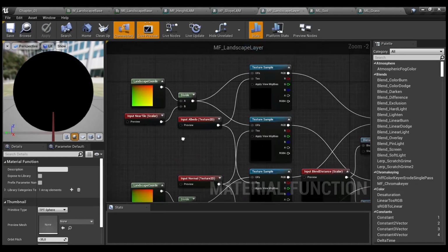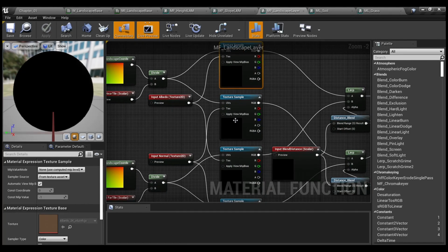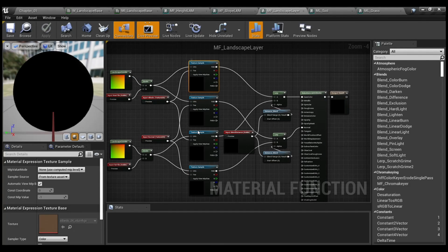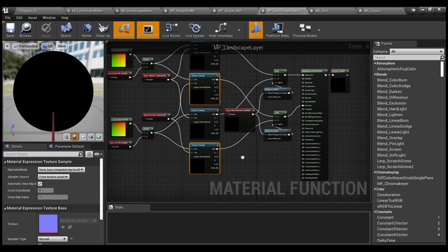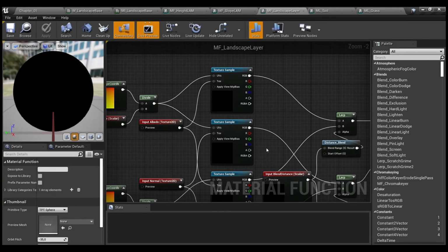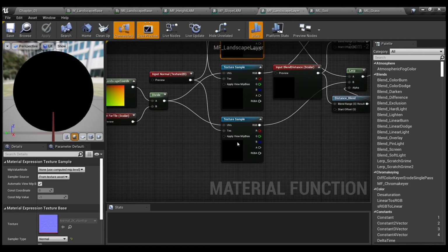but the results are pretty good. So, landscape layer. These variations of texture sample, for both this one and this one, in both cases, are some sort of macro variation. So we will receive the proper results when viewing our landscape from a close look and from the far view. So make sure you have duplicated the base color here and here, and the normal map here and here.